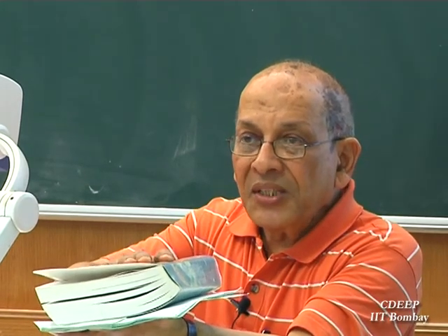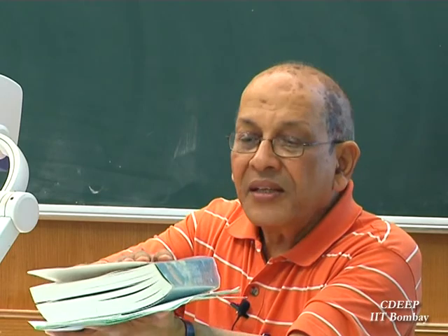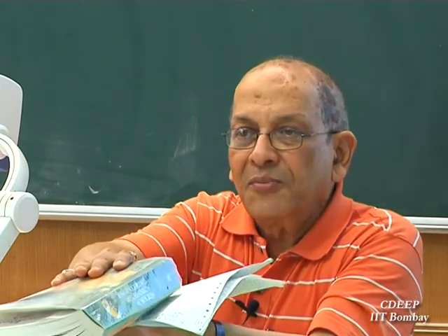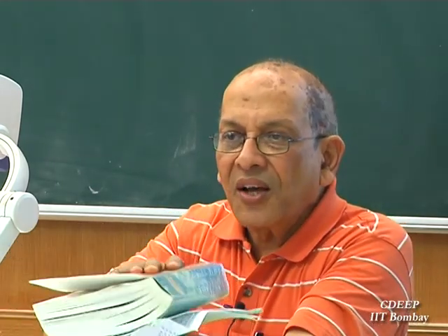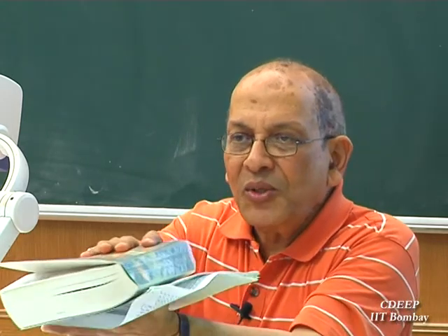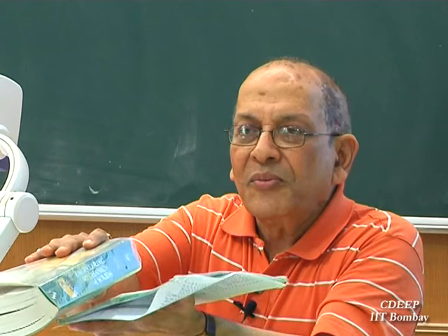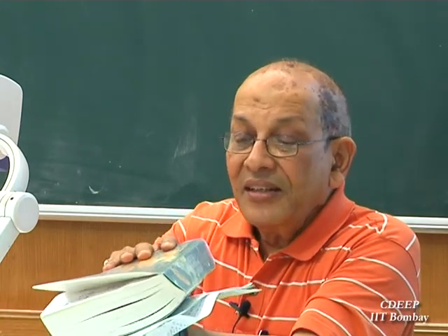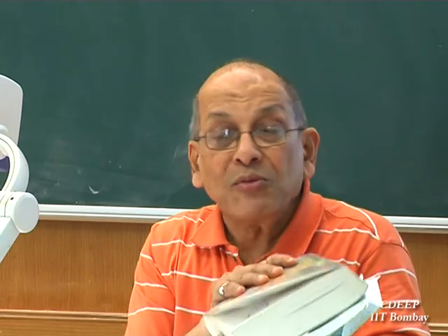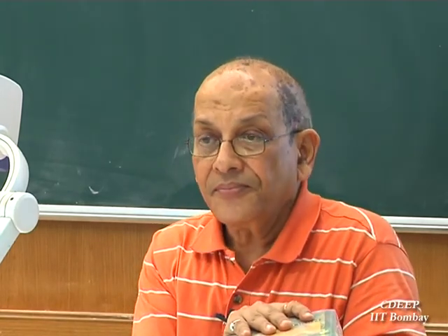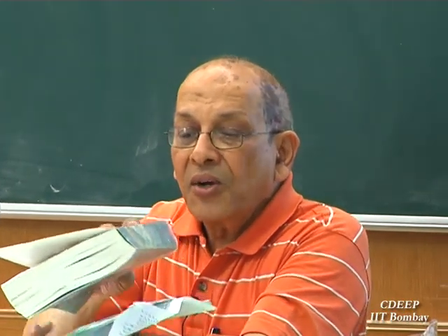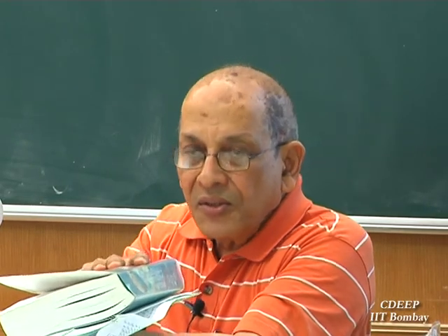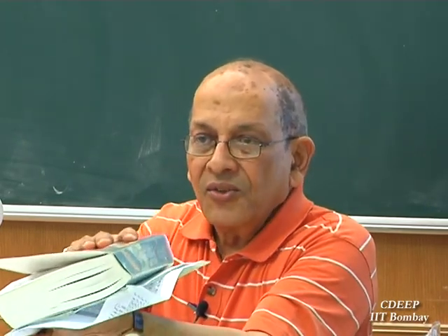If the shear stress is too much, then what will happen? This top portion will just move like this, and failure will occur. Newton's first law, it will start moving and then it will be complete failure, in shear. So again we don't want the maximum shear of the basic material to be exceeded at any point, because otherwise one plane will move over the other in that direction. That is why we want to find out maximum shear stress on the plane.